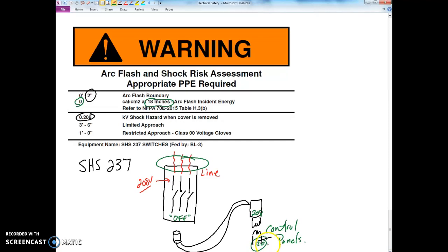You can still get shocked, okay? But we do use finger-safe terminals and things on those panel boards to minimize that effect. And I don't ask you to measure voltage. If we ever need to measure voltage, you'll see me doing it with hot gloves and a meter.